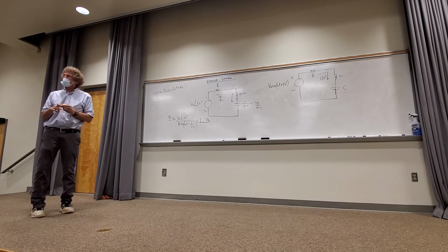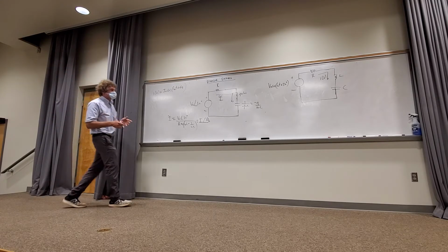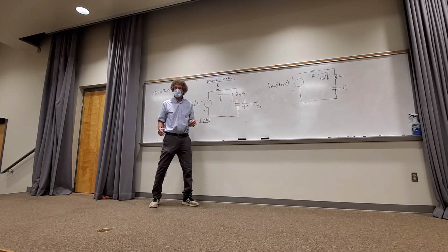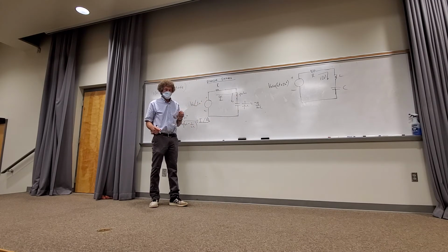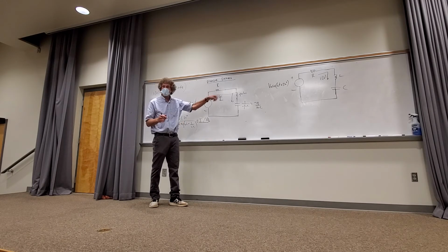When you go for your interview, at some point you go to a power company, some of you IEs especially, and they're going to give you something like this. They'll give you an L and a C and a constant voltage, at a frequency with a given magnitude, like 10 cosine of 377t plus 12 degrees. And they want to see if you understand how to get the current. The reason is, if you're just a physics person, you've got to write a DiffEq.